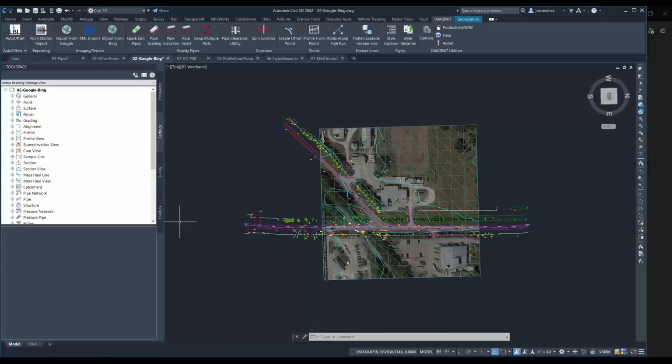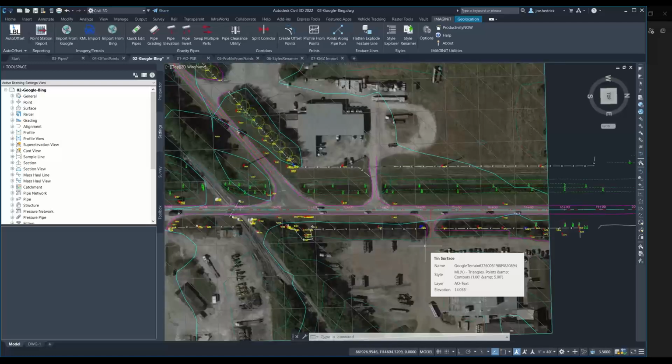The style that we pick is the default style set in your drawing command defaults. And as you can see, that was pretty quick. The image itself is stored in the same location as your DWG file. So you will note if you try to run this command and haven't saved your drawing, it will make you save the drawing first, and that's just so that we can get a location for the image.